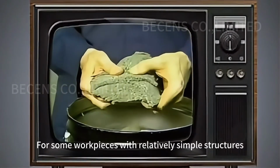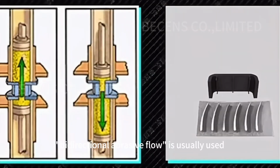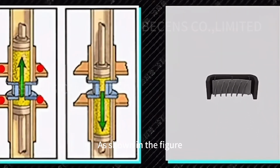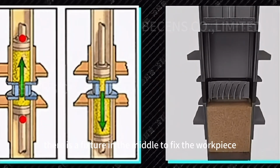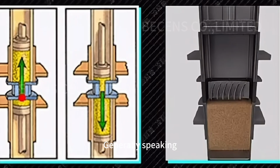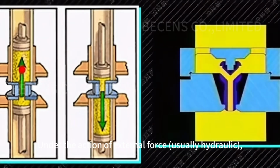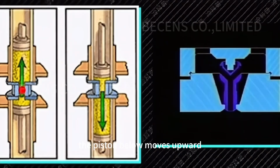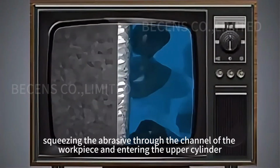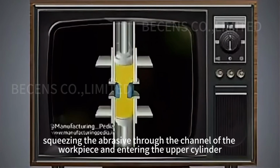For some workpieces with relatively simple structures, bidirectional abrasive flow is usually used. As shown in the figure, there is a fixture in the middle to fix the workpiece, and there is a piston above and below. Generally speaking, the abrasive will be filled in the lower cylinder. Under the action of external forces, usually hydraulic, the piston below moves upward, squeezing the abrasive through the channel of the workpiece and entering the upper cylinder.